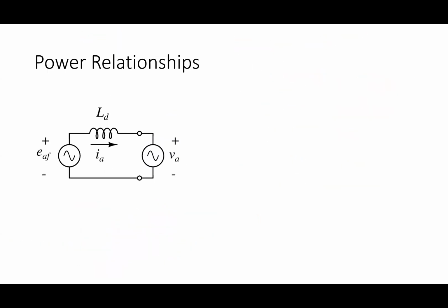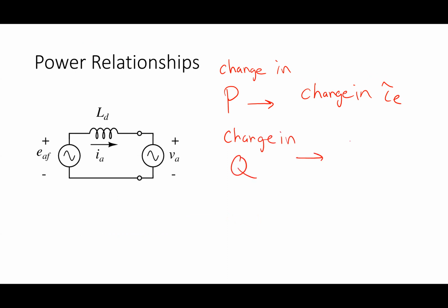So if I'm told to change the power, a change in P means a change in torque, and a change in Q comes from a change in I sub F. Okay. That's our basic relationship.